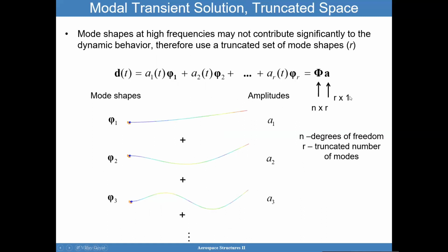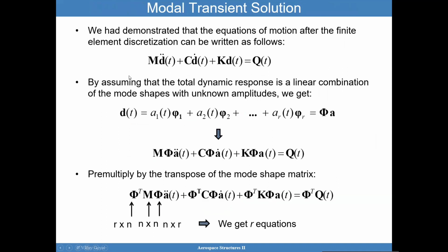You get N by 1. So you get the full information about every single node in your finite elements. It's fully known. And so you know how every single one of those nodes of that rocket model, which is millions of degrees of freedom, behaves through this formula.